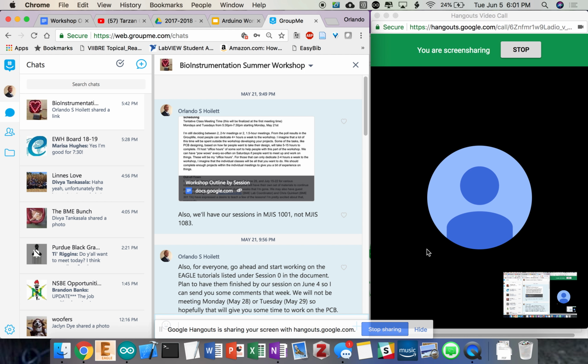Remember we talked about how digital pins can write information, but they always have some sort of output current, sink and source. Source means how much current they can provide to the system. Sink is how much current they can receive, and that's basically acting as a ground source.